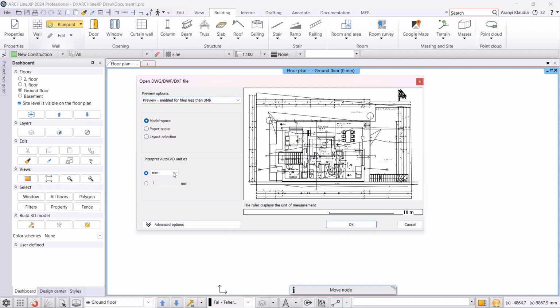The blueprint feature automatically generates BIM models from DWG floor plans. This intelligent tool interprets 2D drawings and transforms them into 3D models. The algorithm reviews the drawing, analyzes it based on the specified wall and opening limits. In the next step, it transforms these into real architectural elements, creating walls, doors, and windows. For CAD drawings, the algorithm can achieve a 90–95% recognition rate.